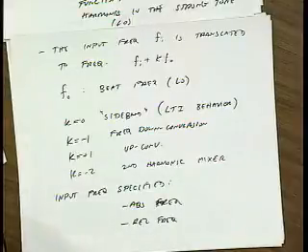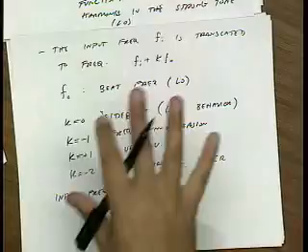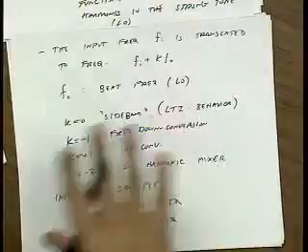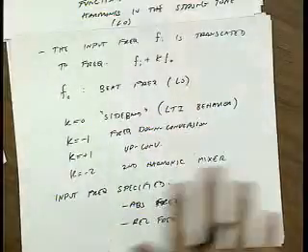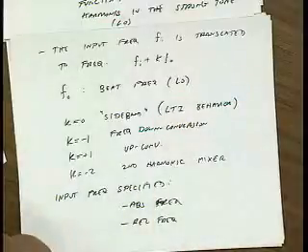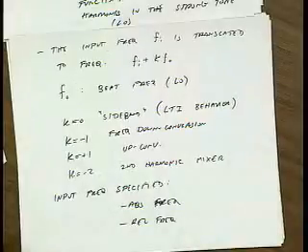Questions about PAC? Now here's what I suggest you do: the first time you run PAC, run a very simple circuit that you've analyzed by hand, let's say a simple switching mixer, and you know all the right answers. You know exactly what the conversion gain should be to the first harmonic, to the second harmonic, and so on. And check it to make sure you're running it correctly. There are also some good examples that come with Spectre that you can try out. Okay.